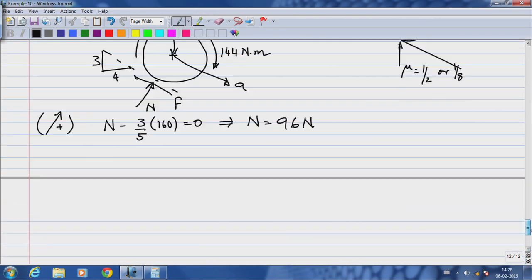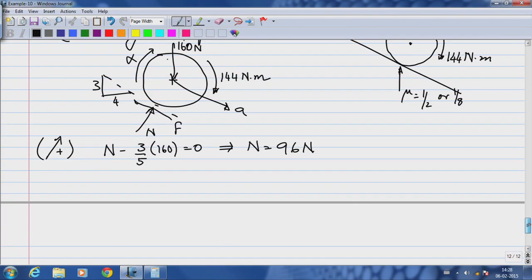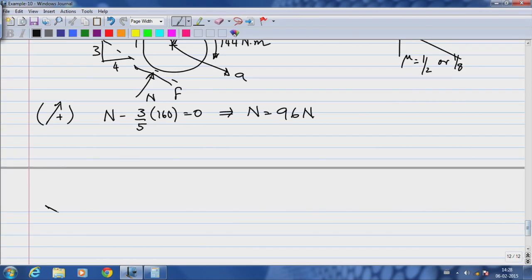That did not change. We are going to assume downward force is positive and do a force balance in the downward direction. So, 160 into 4 over 5 minus f equals 160 over 10 times a.